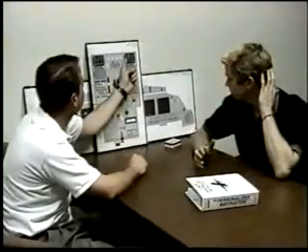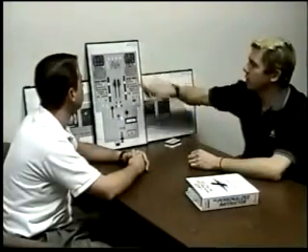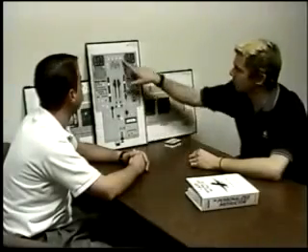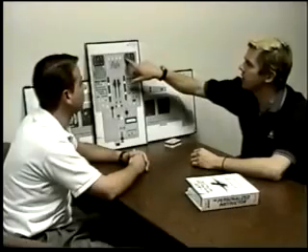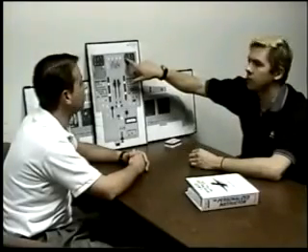Same scenario, but you're on a 319 today. VLS is still 128. Mag winds are 330 at 15 and runway 33. How's V approach calculated for the 319? Okay, the only difference in all of these is that on a 319, it'll be VLS plus 5 or VLS plus a third of the headwind that's set in here, whichever is greater. On the 320, we added both. Here, we're only going to add the higher of the two. In this case, with a VLS of 128 knots, mag winds of 330 at 15 on runway 33, a third of those headwinds is 5 knots. 128 plus 5 is 133.